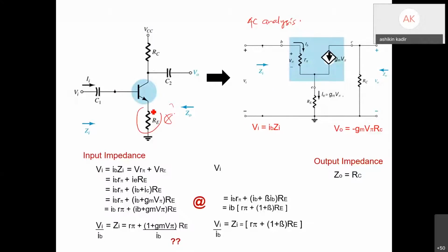Firstly, at middle frequency, you have three terminals, C, B and E. From C to E, you must draw the current-controlled source, gm v pi, with the arrow in diamond shape pointing to the emitter. You label this gm v pi, and then from B to E you have r pi and v pi.